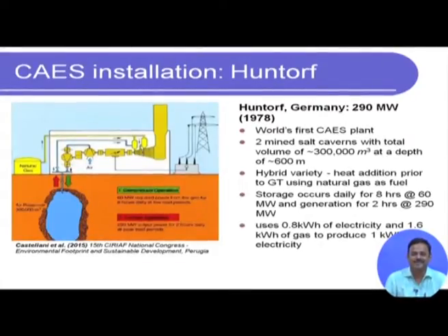It is not an anomaly. You remember that we are adding energy over here through this combustion process. Like in a gas turbine, the work that we get out of the turbine, part of it is used to run the compressor, right. So, the work that we get out of the turbine is definitely much more than the work that we put in for the compressor. Why? Because we add additional energy to the system through the combustion process. Here also we are doing the same. We are having a combustion chamber, we are burning natural gas and adding energy to the compressed air. So, that is why we are getting 580, whereas the stored energy over here, not considering any losses, which is again not correct, is only 480.